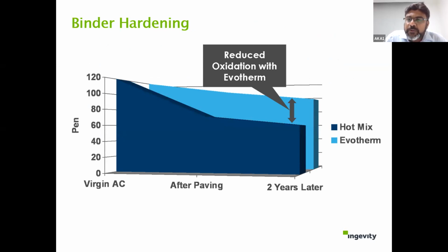When it is still 10 or 20%, it's okay, because out of the whole system it is only 10 to 20%. But when you're talking about 30-40% RAP, high RAP, then a considerable amount has already been oxidized. So the chances of fatigue cracking, brittleness, and other distresses can be very significant when you use high RAP.